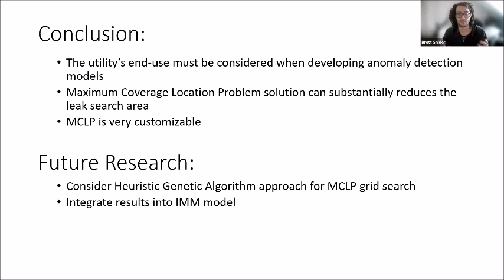We've already started to develop this, and having a variety of performance indicators that evaluate these decisions, we can start to see which valves should be closed, which pressure settings should maybe be adjusted, should we implement overflow or overland bypass pipes, etc. These are a variety of the options that we can analyze, and then by analyzing this, inform the utility of the most effective decision.